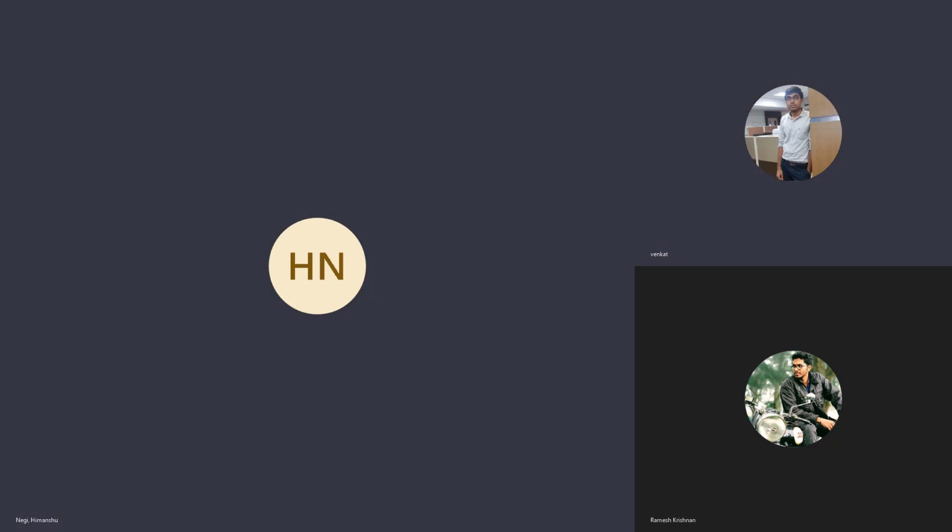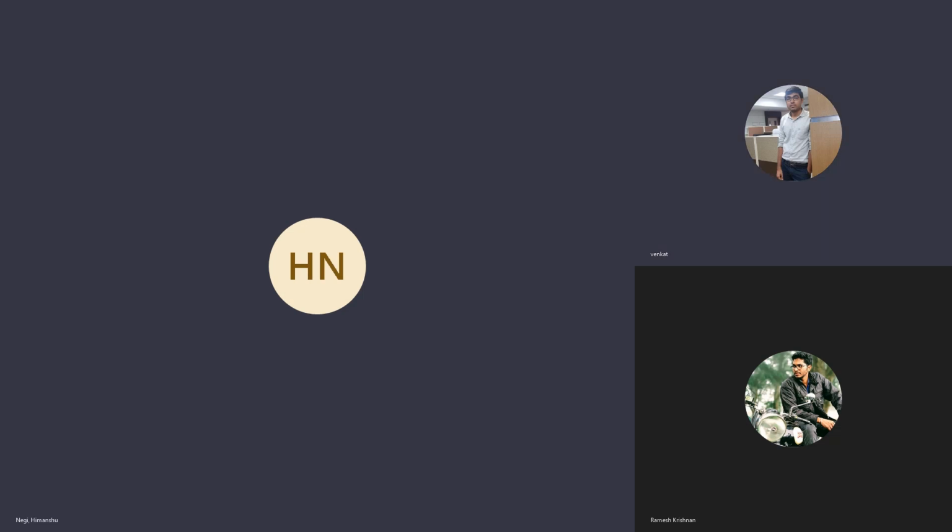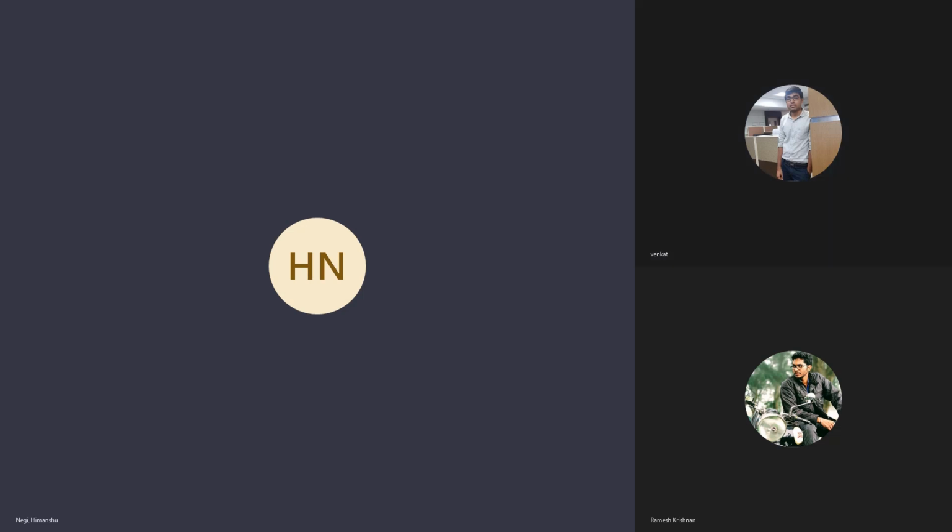In each junction you've got a link box here, right? And that one has an SVL, and then that's earth. So this is another cable here, the third cable, which goes to a particular place, and that place is this dotted conductor, an earth mat, to protect this joint, and this also protects a person operating this, right?